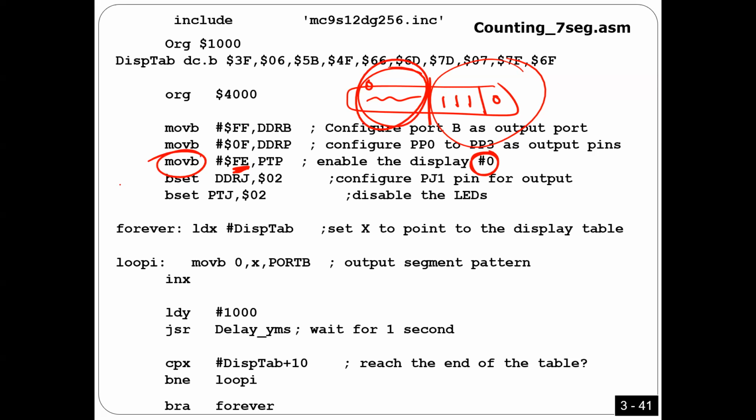If you do the same thing, this is going to create a problem in the test. Why? Because I'm using RGB. So what can I do now? I'm going to tell you. Please try. You have to be very wise when you use move, because move is going to change all the bits. Instead, try to focus only on the bits you want to change.